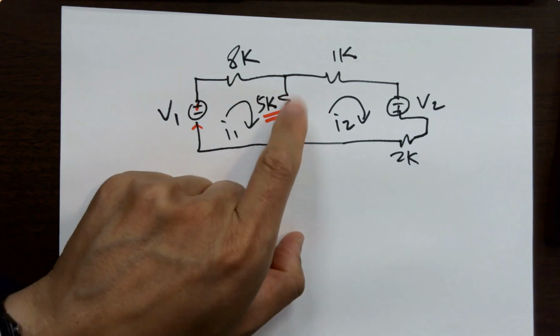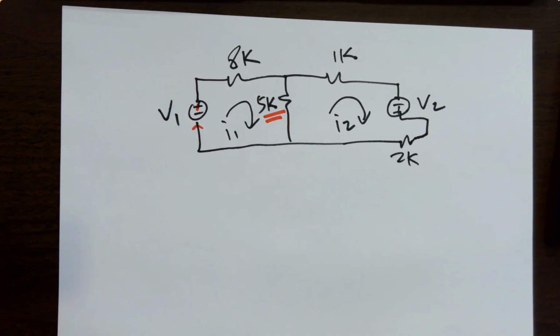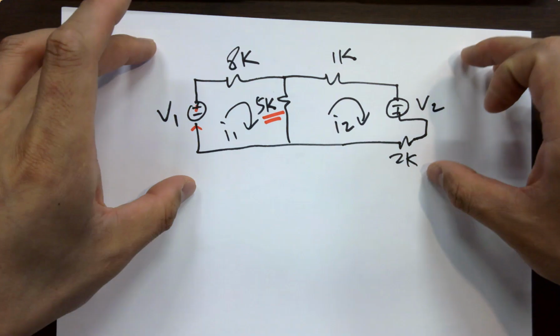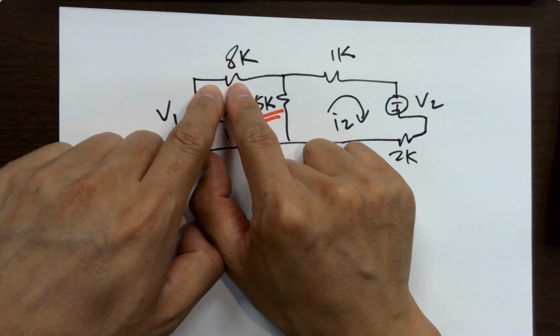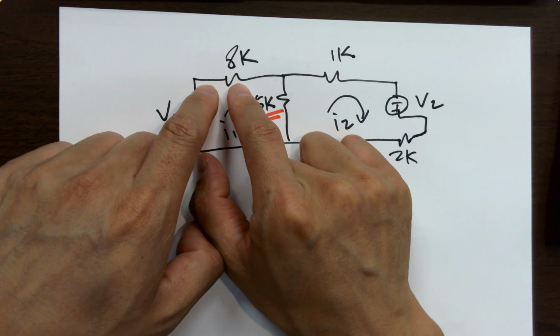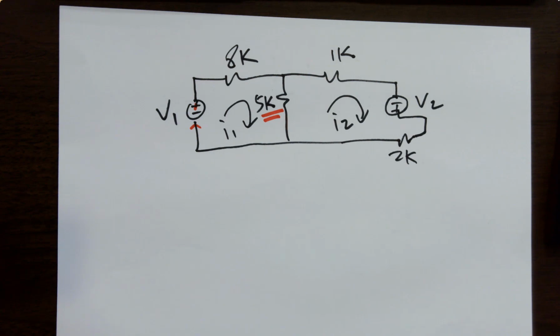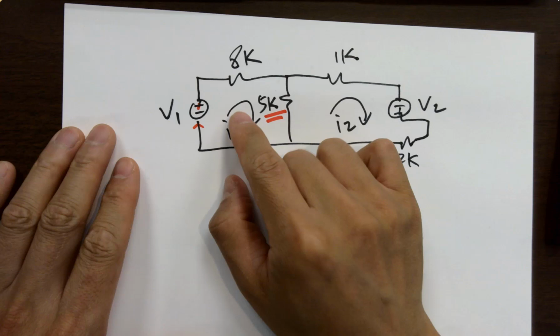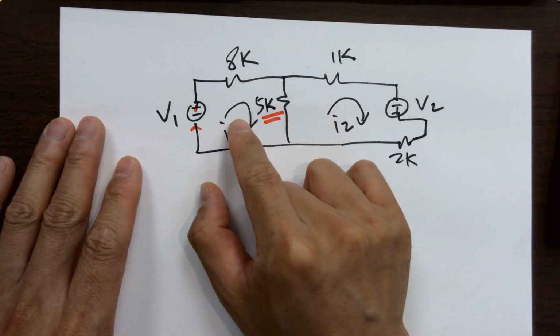So what would that be? Again, when you are dealing with the mesh current method, keep in mind, it's not something like we label it, we know it's exactly physically flowing through that single resistor. This is like a semi-virtual current. You know what I mean? So eventually it works. When we move down the road, you will figure out why. But now just remember the procedure here, and that's the method you want to know how to use, right?